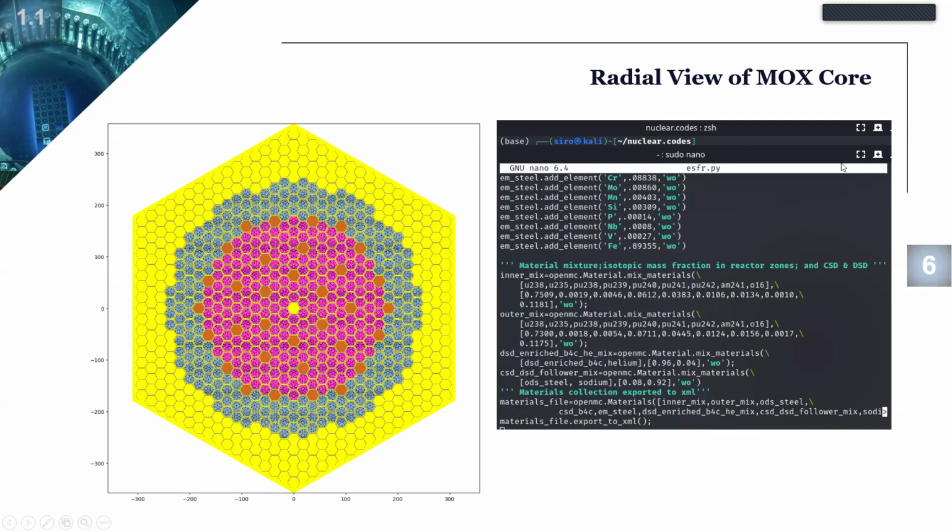And then the brown subassemblies represent what's called the CPS system, also not just arranged at random. There are the control shutdown devices, which are normally used in normal operation of the reactor core. And the diverse shutdown devices are the ones we use when we want to facilitate what we call emergency shutdown, or known as a scram.